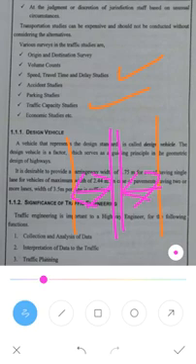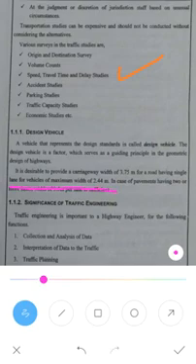So we design the vehicle for a width of 3.75 meter for a road having a single lane, for a vehicle having a maximum width of 2.44 meter. In the case of a pavement having two or more lanes, a width of 3.5 per lane is sufficient. That is known as design vehicle.